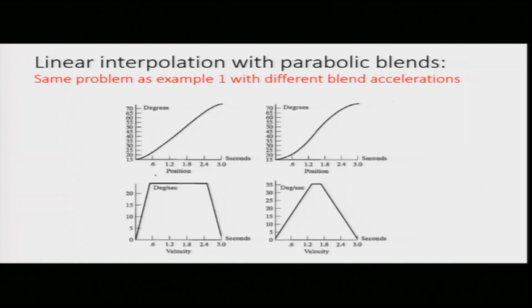So, this is my position graph. This is position, this is case 1, this is case 2. In case 1, we find that the variation of the position, theta, starts like this. The parabolic section is very small, then there is a long linear section, then there is a parabolic section again. Now, in case 2, where the motor acceleration is low, the parabolic section is more pronounced.